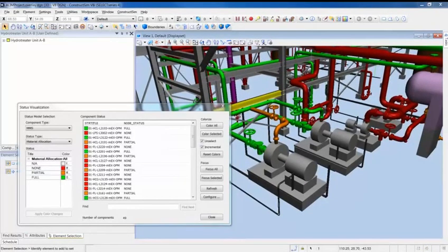As this valve is an erection item, by this we mean it will be installed on site, it will not stop us fabricating the pipe or indeed installing the rest of the pipe. So we can instruct the material management team to allocate the remaining materials. This is especially important as following further checks, we discover that the pipe needs to be installed so we can carry out a site weld further down the line. And this site weld is key to positioning a piece of equipment.